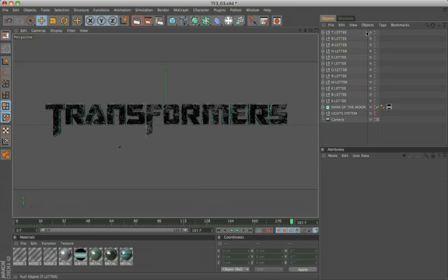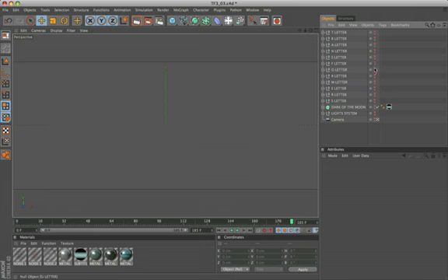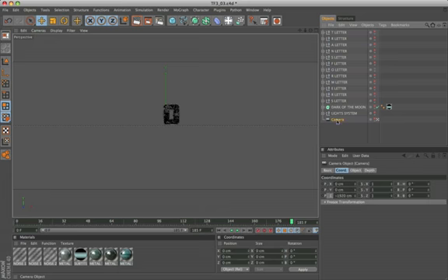To appreciate the animation, you need to insert an animated camera. Follow the parameters on video. To make the fluid movement of the camera, we'll set keyframes in reverse mode, taking care the activation of keyframes is alternated.